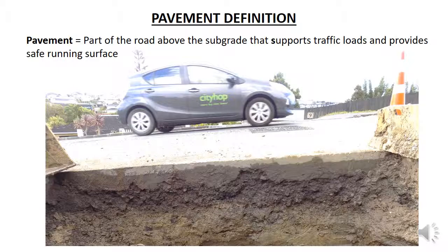This photo shows a section through a flexible pavement. You can see there have been several surfacing layers applied over the years. The top surface is presently asphaltic concrete. You can also see a 150mm thick base course layer beneath the surfacing. Beneath that is a clay subgrade.